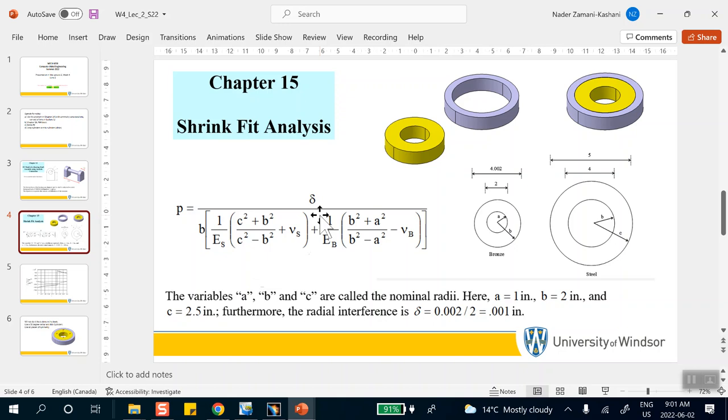Okay, so it's one of those problems that actually has an analytical solution, right there. And what do we mean by that? One of the things that you want in this shrink fit problem is to know how much force, how much pressure is at the interface between the two. How much pressure is the steel putting on the brass, and how much pressure is the brass putting on the steel trying to expand it? Okay, that number is extremely important, because if it's too low, and this is, for example, a shaft that's shrink fitted hypothetically inside of the disc, when it turns, it may come off.